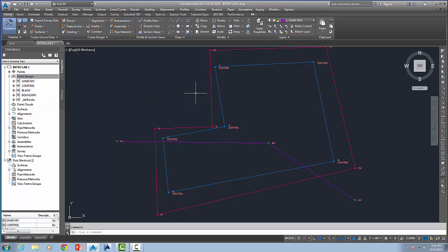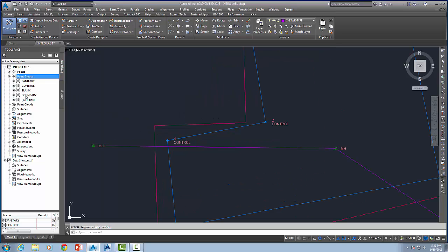The reason is you have to force a regen in AutoCAD. If you type in RE, it will fix that for you. So you notice that it really does reflect that hierarchy. It just sometimes doesn't want to generate a regen for you, so you can force that anytime you want. RE, just remember that one.